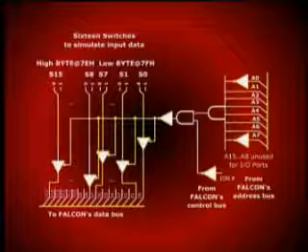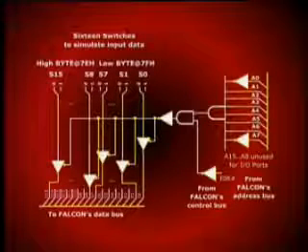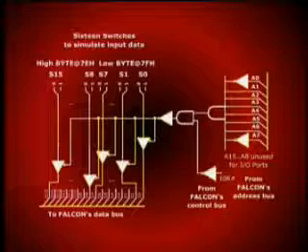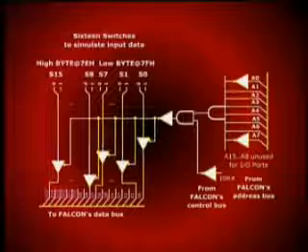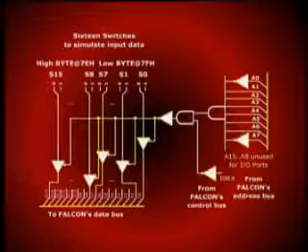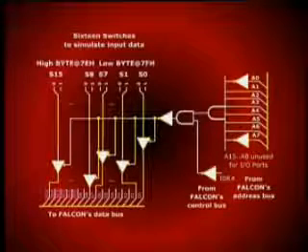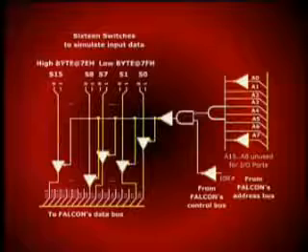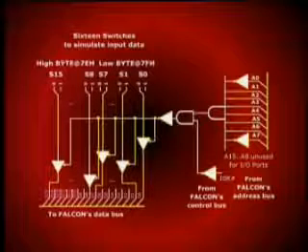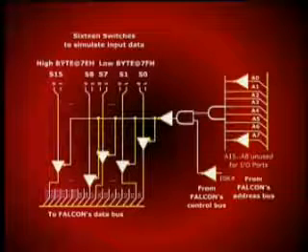The output of this AND gate through an inverter enables the lower 8 tri-state buffers from D0 up to D7. Therefore, this implementation independently addresses the least significant byte and the most significant byte of the data bus.